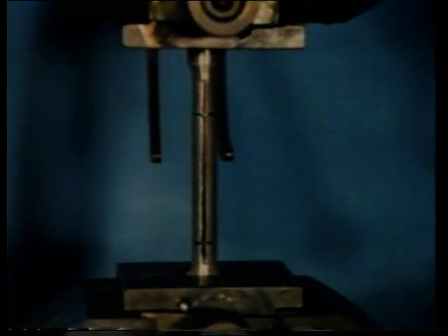To find out how alloying has affected the strength of the aluminium, we must cast a suitable test piece. To compare forces, the alloy test piece must have exactly the same dimensions as the aluminium one we tested earlier. Now for the test. Well, that's where the aluminium fractured, but as the force is increased, the aluminium alloy proves to be much stronger. By forming an alloy, we've brought about a useful change in the mechanical properties of the aluminium. We've increased the tensile strength.